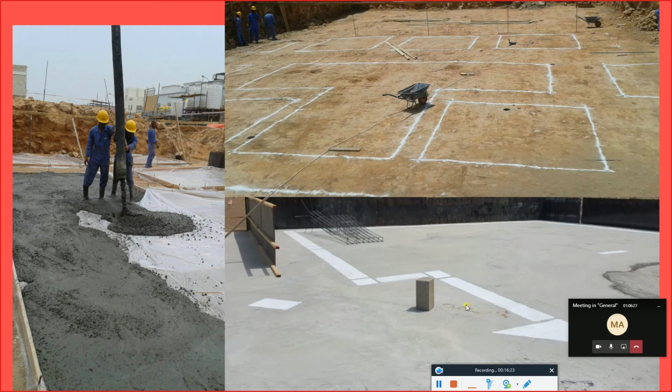Okay, this has been done for all the area, and this normally happens if you have, let's say, a raft foundation all over the area, or the column, isolated and combined foundations are very close to each other. Now here we can see there are still spaces. So why would I put a BCC in the empty areas? I'd be losing more money.